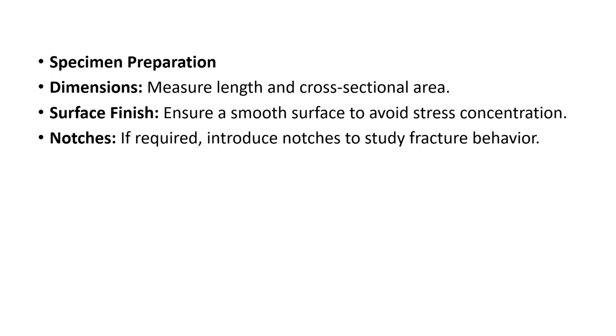As per ASTM standard, specimen preparation is required. The dimension is important to prepare the specimen, that is, measure length and cross-sectional area. Because strength is nothing but load upon area, it mostly depends on area. So length and cross-sectional area are important. Second thing is the surface finish. Ensure a smooth surface to avoid stress concentration. A smooth surface is required to avoid stress concentration, so surface finish is important. And third one is the notches. If required, introduce notches to study fracture behavior. Notches are provided to study the fracture behavior.